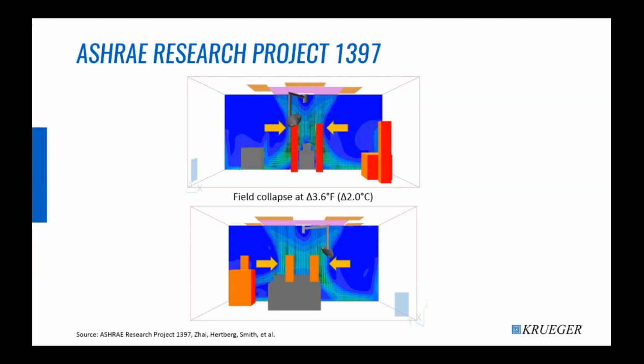The amount of collapse and acceleration is affected greatly by the temperature difference between the supply air temperature and the room air temperature. The collapse is also referred to as coalescence. The amount of collapse increases as the delta T of the cool supply air increases compared to the room ambient temp. One of the issues that this also creates is potential for entrainment of contaminated room air at higher delta T. This occurs when air outside the primary diffuser array is entrained into the laminar airflow pattern and then blown down towards the surgical table. This is a big concern in regard to infection prevention.